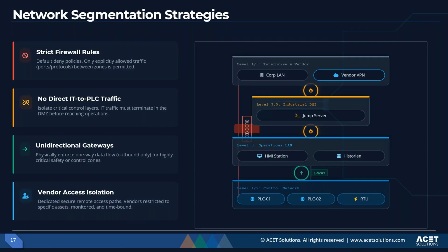Let's suppose the MES in the IT should not talk to the controller. Instead, the MES pushes workflow work orders to the DMZ application broker. The broker synchronizes this with the SCADA in the operational zone, which then orchestrates the changes to the PLC. PLC IPs should not be routable from the IT, so that any outbreak in the IT will not reach the controller.